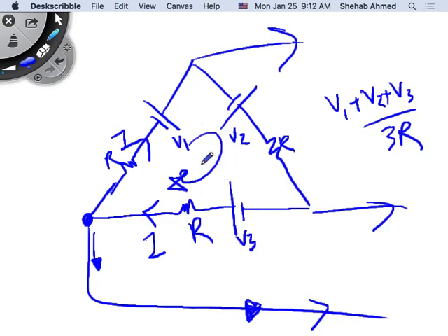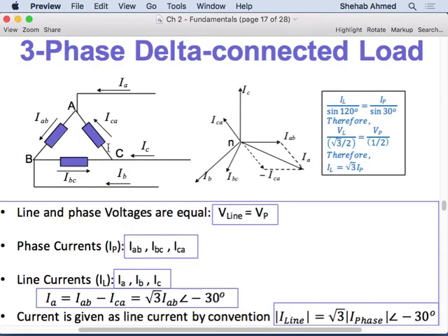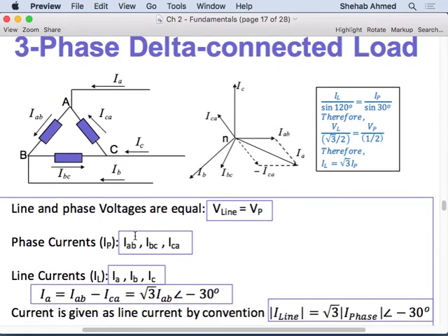If these are not voltages that are 120 degrees apart, then when you add them up, there will be some voltage existing, and you close the loop, there will be some current circulating inside the delta. That will not go to the loads. Connect the load, nothing will happen. And this will only heat up the system. So that was what I was trying to say.